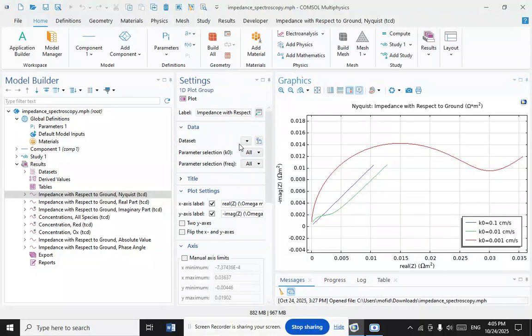And what about corrosion and material science? The first is corrosion. Electrical impedance spectroscopy evaluates the durability and corrosion rate of coatings and is used on-site to assess their integrity. It can detect delamination and water uptake even before visible damage happens.